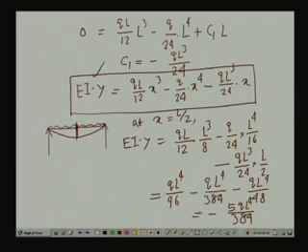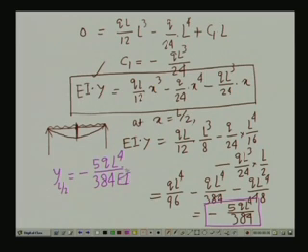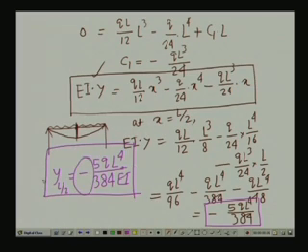Now, in fact, this is the value of the deflection. So, y at L by 2 equals minus 5 q L 4 by 384 E I, taking E I to the other side. So, this is the value of the deflection at the center of the beam. Here you note that we have a minus sign. This indicates that our positive y direction is upward, hence the deflection curve is towards the downside of the beam axis. So, this is the deflected shape of the beam.